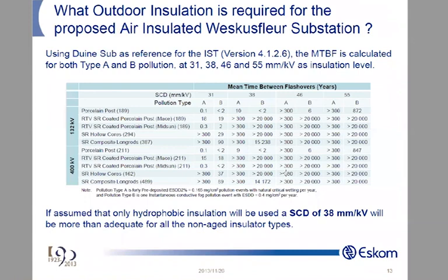Well, let's think about this. Bare porcelain, pollution layer, nice and thick. Does the pollution layer interact with the porcelain? No, inert. Now, is there any way you can improve that? Well, you'll have to wash it off to get the area as small as possible. But now you wash it off, and now it's back again.